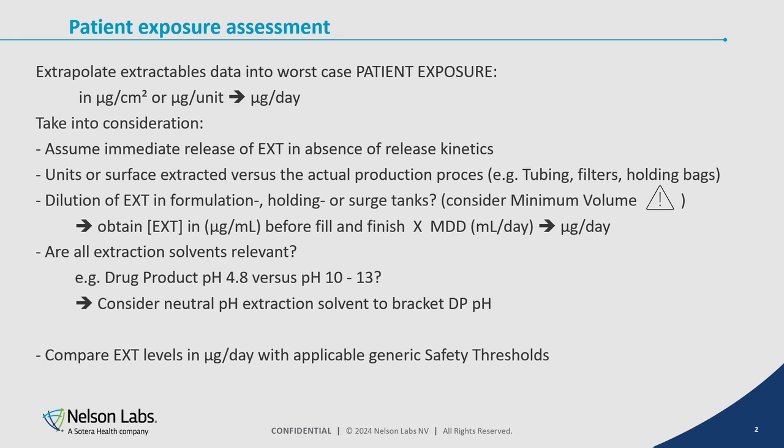What is important, and I put this danger sign there, if you are at the end, downstream before fill and finish, and you have a surge tank, you're not going to wait until the whole batch is there before you start fill and finish. So there's a minimum volume before you start to fill and finish. So the tubing, or also the sterilizing filter extractables, are concentrated in the minimum volume before you start with fill and finish.